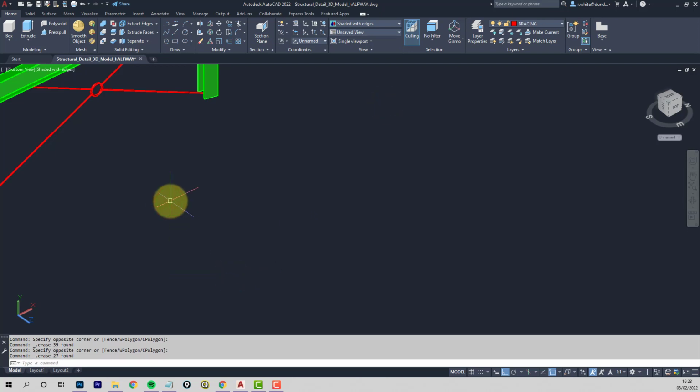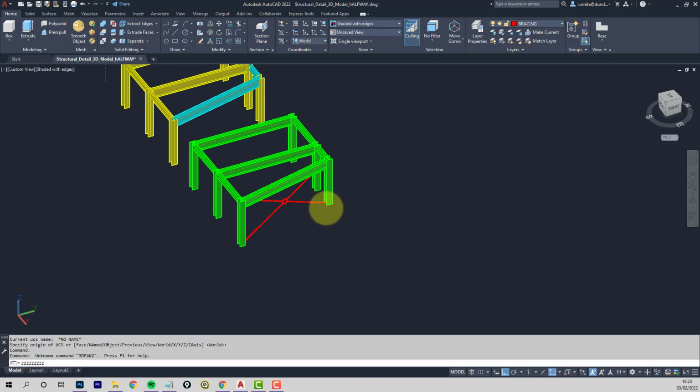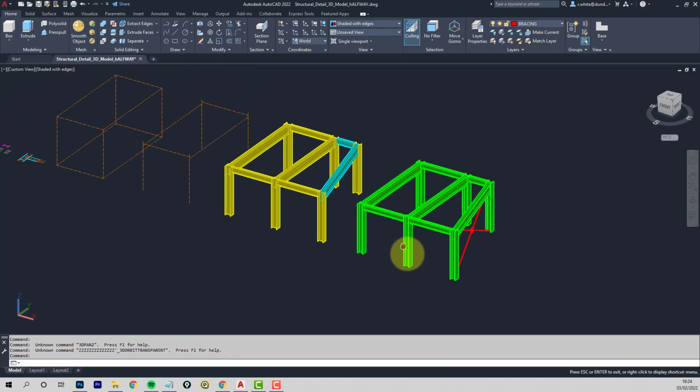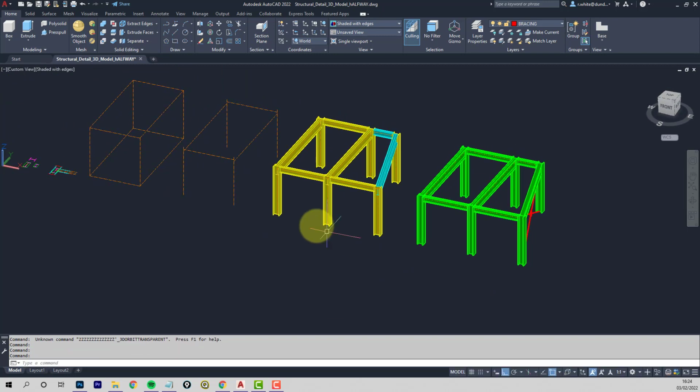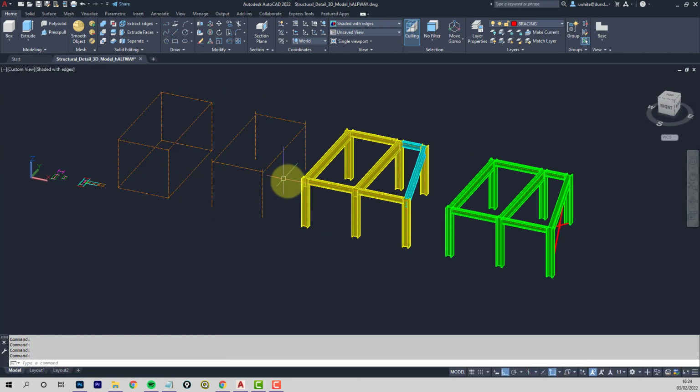And in Rhino, you can actually put the regions back together quite happily. You don't have that benefit in AutoCAD. So if you remember to go back to the world UCS, you can either go here or type UCS and enter twice. Okay, I'm annoyed with myself that I've gone and set that outline. It looks very strange like that, but we'll not lose any sleep over it. Okay, so that's just a little example of different modeling techniques.